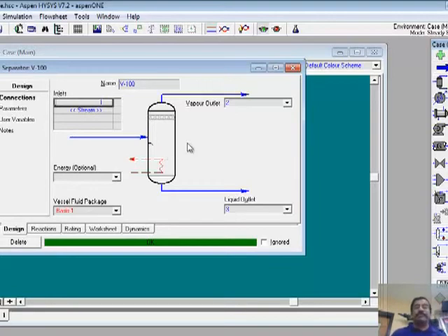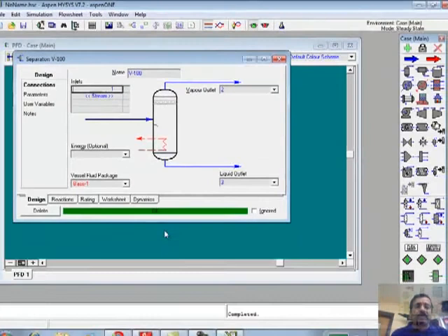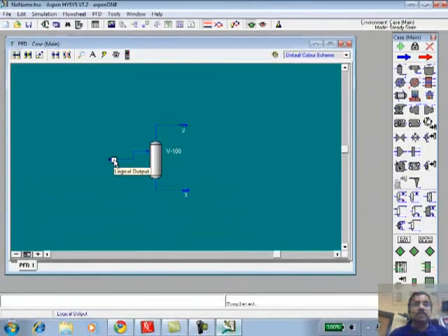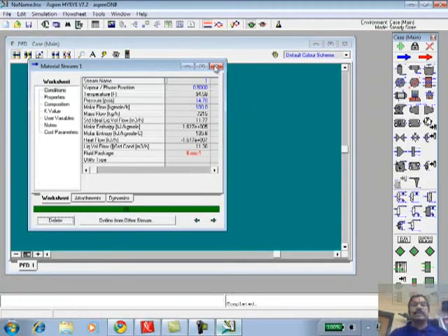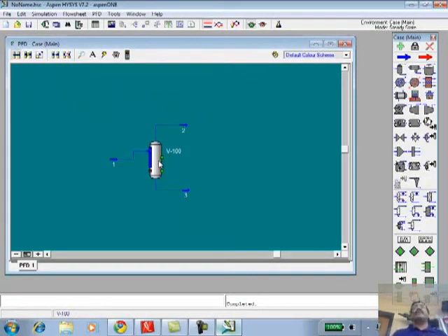What do you think should happen? I just bring the feed that I have defined, which under those conditions is 50% vapor, and dump it into this vessel. It's a mixture of 7 components, equimolar, at a pressure of 1 atmosphere with 50% vapor fraction, at a temperature of 94 degrees. I take that feed and dump it in here. What do you think would happen? Half of them will go to the top, half of them will go to the bottom. Does it say that to us?